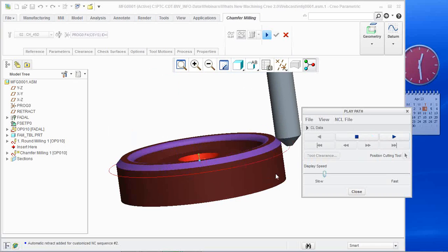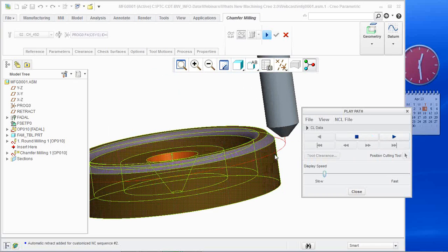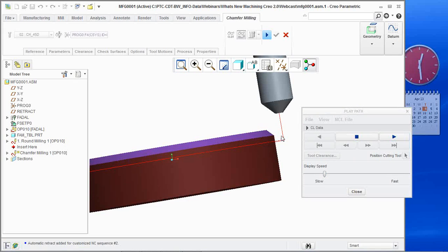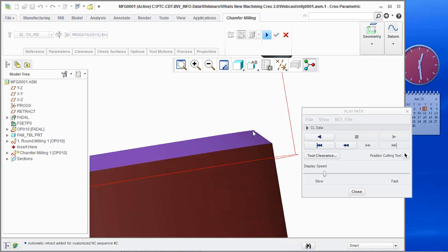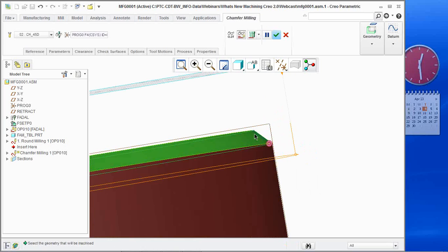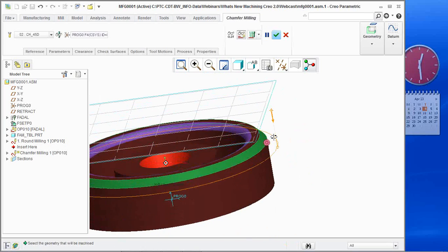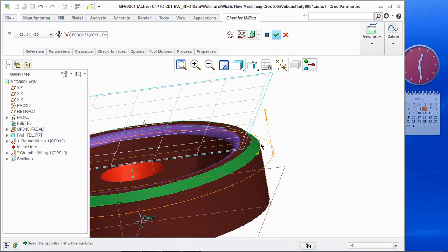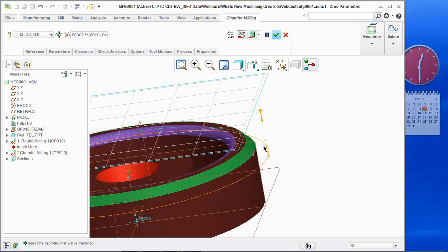Now, one thing that I did learn recently, and again, I think it's because of my site file, because I'm filtering off some parameters, is that it considers the initial point to be essentially the contact point, and then there is a percentage or a value that tells how far up and down the angle of the bit you want it cutting. There's a percentage value between 0 and 100%, essentially where on that point you're actually going to be machining.